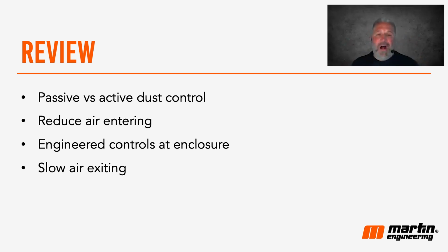Number 3, you want to make sure you use that systems approach. Proper belt support, wear liner close to the belt, urethane if you can, and then a skirting system to really seal that air inside that enclosure, and then finally slow that air as it exits.